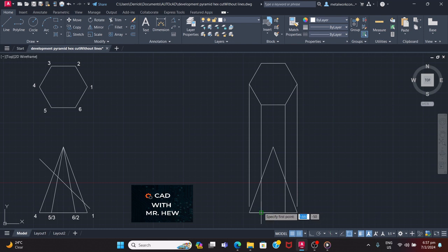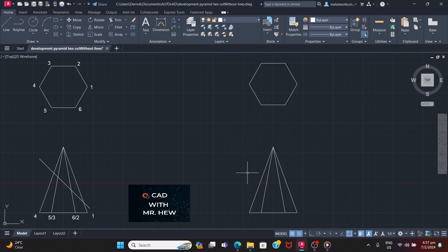All right, let us darken this slope sides, and good. So that's our given front elevation. So we have completed the first part of the question, which is to draw the given view, which is the front elevation of the hexagonal base pyramid that is cut at an angle.